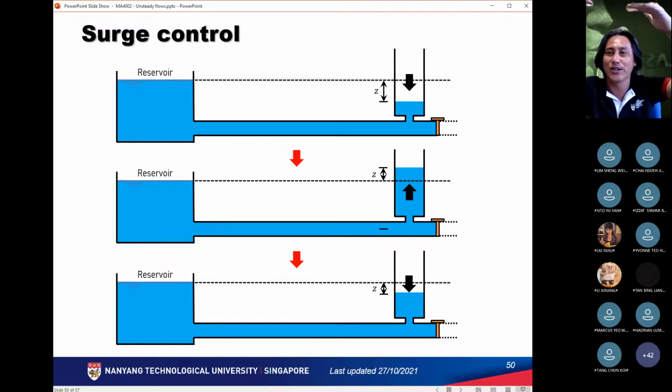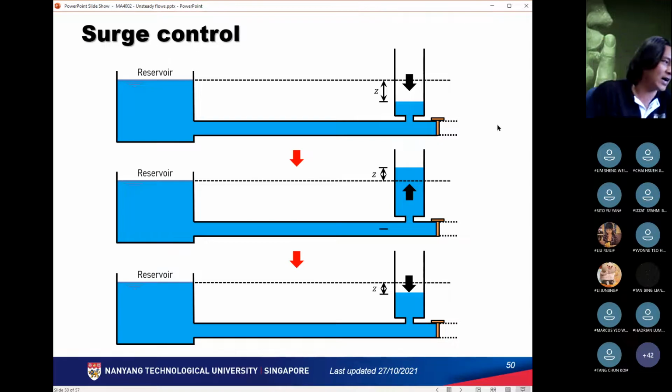Because, like I said, the water surface is a dynamic one, it's going to undergo oscillation, as you can imagine. The pressure waves are traveling along the pipeline, up and down. So surely the variations in the pressure are going to cause the amount of water in the surge tank to vary, gradually, as the pressure wave gets damped.